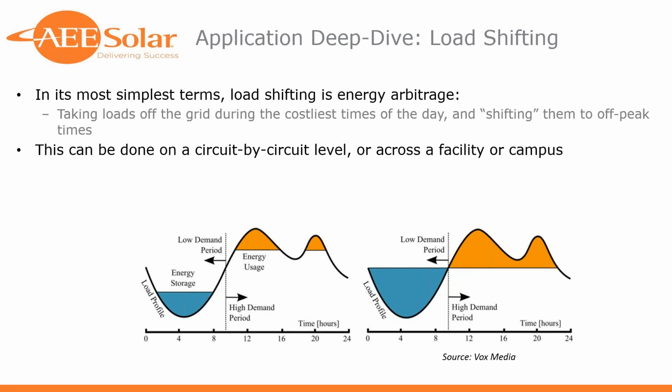You're letting those loads draw from storage first, while they're turning on, while they're rotating mass, when the highest peak is occurring. Once they get to a steady state, your contactors and circuits are going to close. Then you're drawing power back from the grid again, and your storage can recharge.